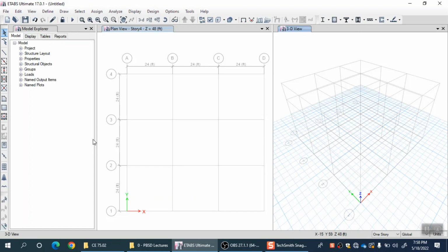So if you have 20 types of beams having different amounts of steel and cross section size and a material associated with them, then you should define 20 hinges and then select one by one all those beams to which you want to assign a particular hinge which you have defined. So the program will generate additional hinges and assign them to those particular selected beams, right? So now we shift to the auto hinge option, in which we do not first define a hinge and then assign.